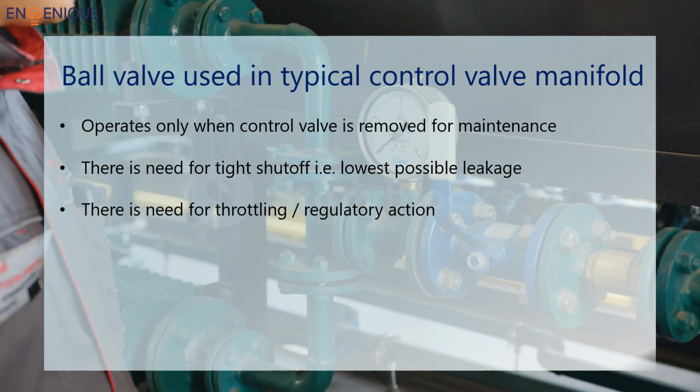Need for throttling or regulatory action when control valve is removed for maintenance. Easy manual operation. Considering these requirements, ball valves are most suitable for these types of applications. Advantages of using ball valve.